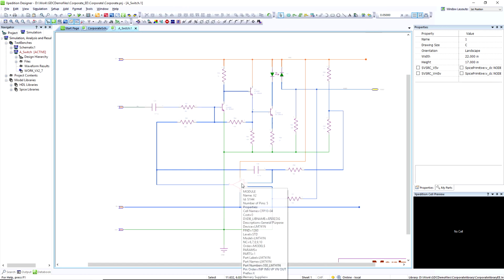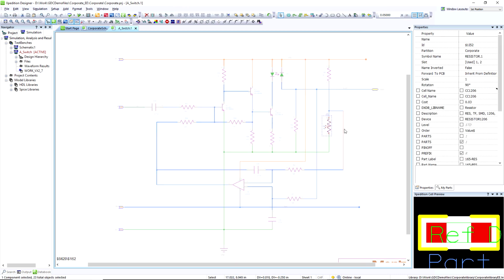So in the case of a resistor, it'll see that the reference designator is R, so it knows it's a resistor, and it'll add all the appropriate properties for that. So that'll take care of like 90% of the design, all the resistors, capacitors, inductors. You can add in additional modeling information to get more complex parts. So that will take care of setting up parts for simulation.